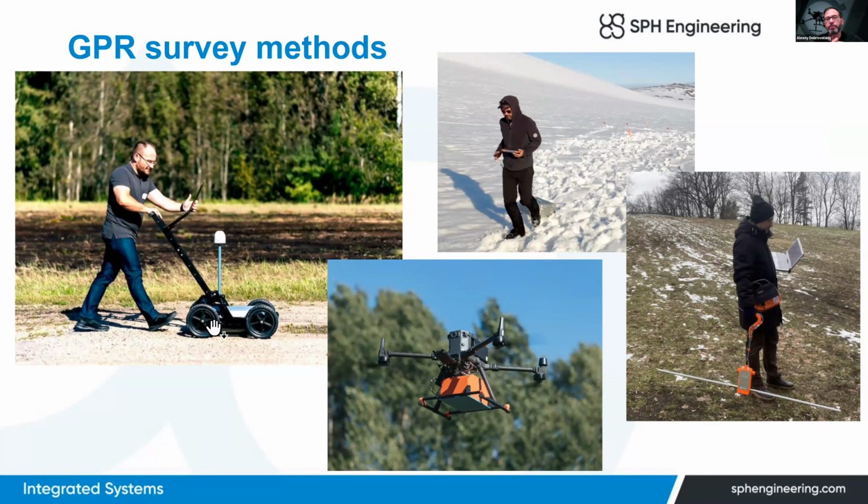Because the majority of GPR applications are inside cities, on streets, on squares, to find underground utilities. It's the most popular GPR application. That application means quite confined spaces, not very big survey areas. Sometimes it's just a few square meters before new digging. And in such surveys, in such an environment, a cart with GPR is the most optimal variant to use GPR.